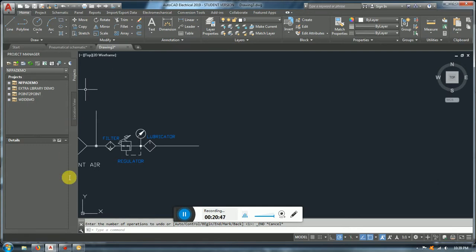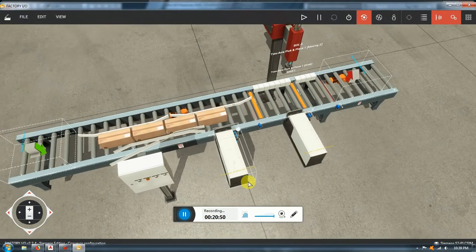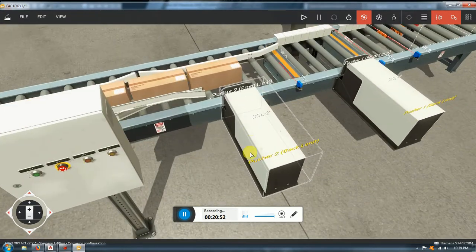In this case, for all of them, the cylinder is going to be double. Depending on whether the air goes in the back or the front, it's going to retract or push forward, or extend, sorry. If you have a single, it has a spring, so you only push, you only retract or extend, and the spring is going to do the other.